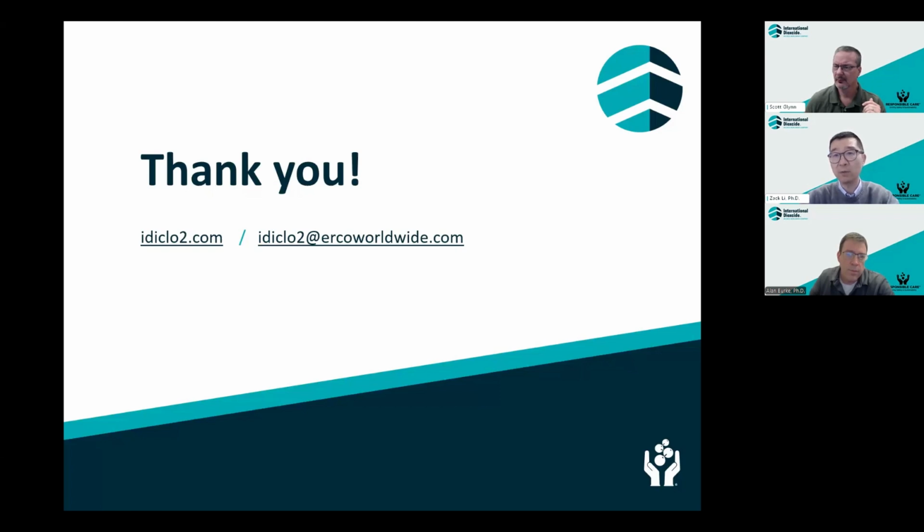Scott and Alan, do you have something to add? Yeah, I'm not aware of any issue with chloride from chlorine dioxide being a problem with manganese. The amount of chloride introduced from using chlorine dioxide is usually insignificant compared to the background chloride concentration in the raw water. Yeah, I would agree with that.